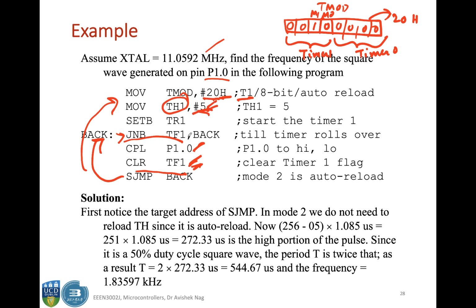The timer is already on, so when TF1 gets set to 1, this number is automatically reloaded to TL1. You clear TF1 and keep monitoring it again.